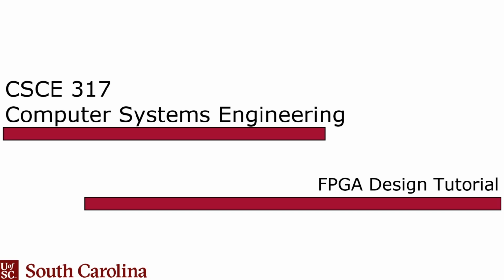But there's a secret feature where, if you don't have a capacitor to ground on the reset pin, you can send a special protocol into that pin, which gives you access to debugging the chip. It gives you full debug access, where you can actually step, you could do a full debug. In order to do that, though, in addition to not having that capacitor there, you also have to have a debug module, a special debugger, which we actually have.